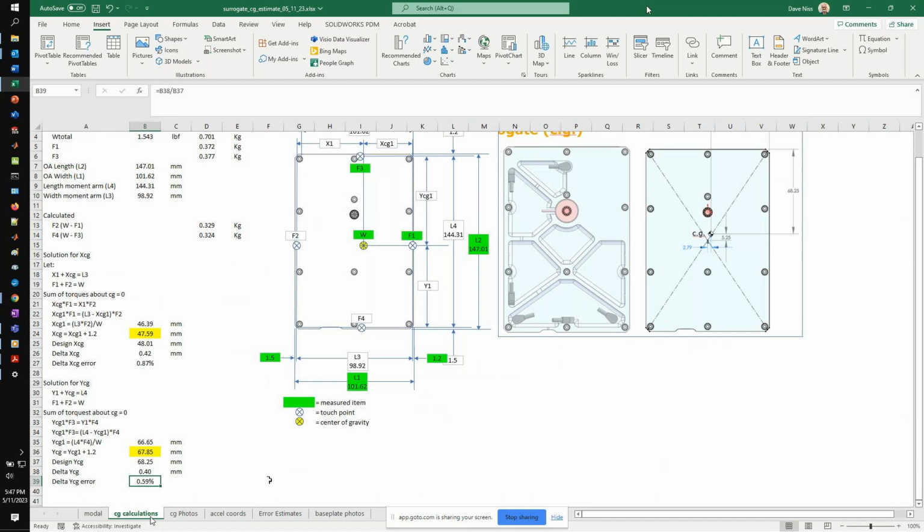So does that mean, what does that mean in terms of, does that impact the manufacturing process, or what's the ramification, I guess? Well, the implication is if you're looking at the linear acceleration values, it's really just the mass, right? If you want to calibrate surrogate A with surrogate B in the linear DOFs, then if one weighs the same as the other, other than the channel errors, you should get the same answer. If you have a difference in mass, then you can have a correction factor to bring your mass back, which you could then multiply the linear.